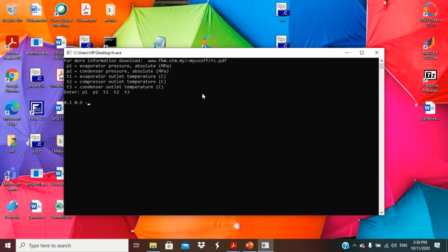T1 is, let's say, -3. T2 is going to be 55. T3 is, let's say, 28. So the program will calculate for you H1, H2, and H3. And automatically H4 is equal to H3. It even calculates for you the COP. It's using the first method.